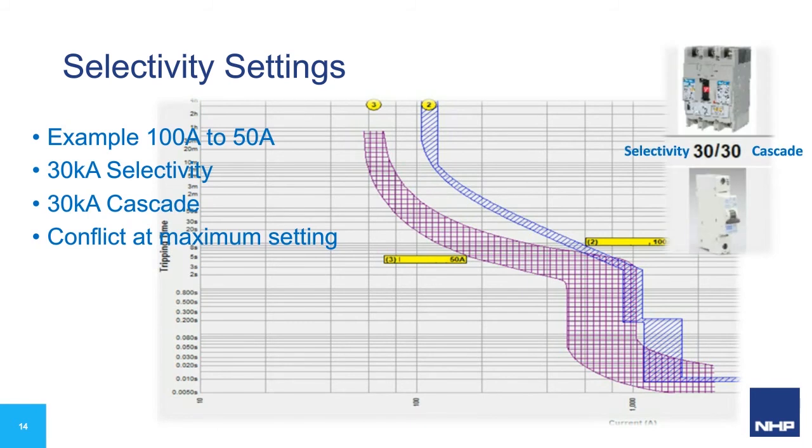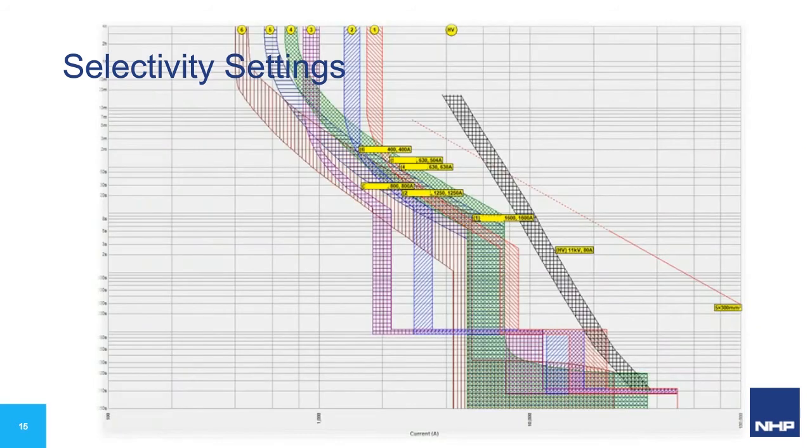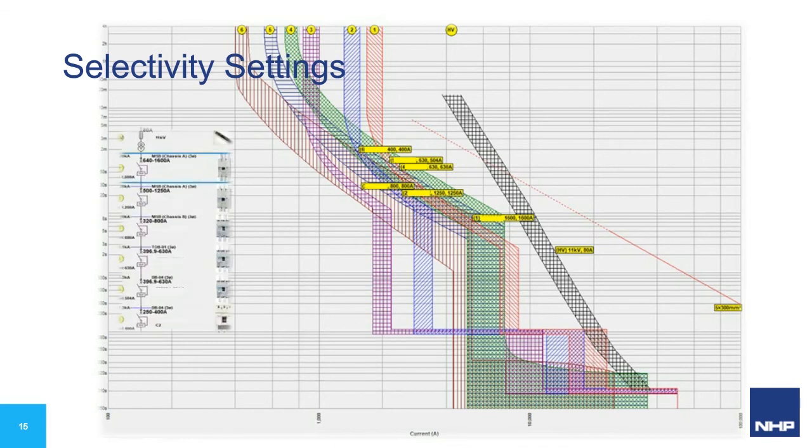So with our structures and operations becoming more and more current dense, the need to reticulate multiple layers of distribution, often with similar or essentially the same settings on protection devices, how can we reduce the likelihood of many devices tripping in the event of a single fault, especially in the low to medium area of short circuits?